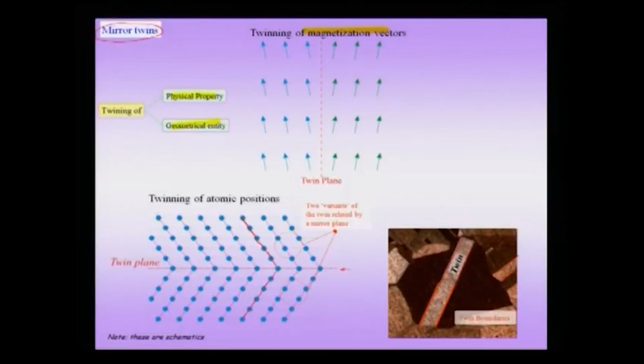But the important point to note here is that the twin itself, the twin region itself, is a volume defect, if you talk about this defect with respect to the remaining part of the grain. So, this is my grain, and in this grain the twin boundary introduces a misorientation of the plane.